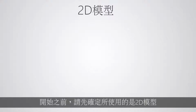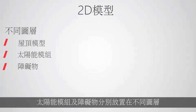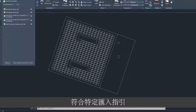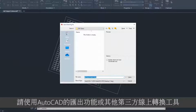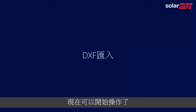Before we start, make sure you are working with a two-dimensional model, and that the model, PV modules and obstacles are each placed in a separate layer in your CAD software. The first step is to ensure you have a valid DXF file that matches the specific import guidelines. If your file is saved in a different format, such as DWG, convert it to DXF using AutoCAD's export feature or other third-party online conversion tools. We're now ready to start.